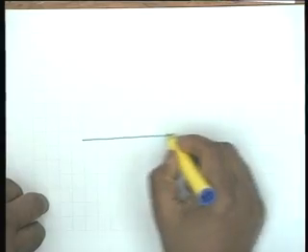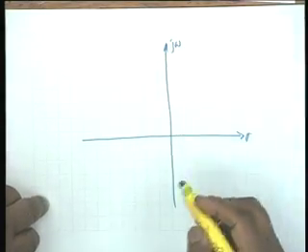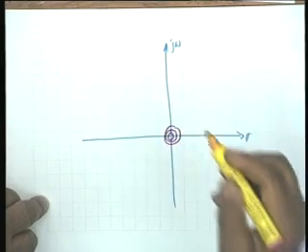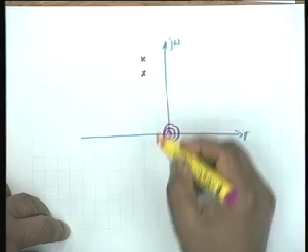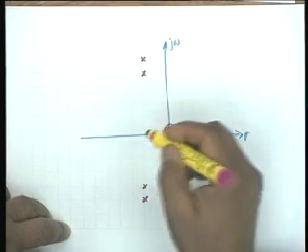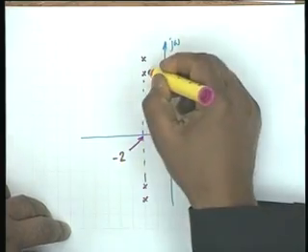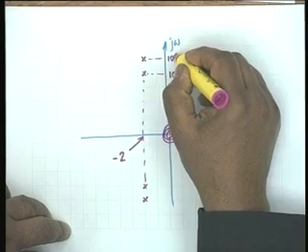If we look at the pole-zero diagram, there are 3 zeros at the origin as in the tuned circuit, and if we exaggerate a little and distort the scale a little, there are poles here and here, where this distance is minus 2, this is 100, and this is 106.